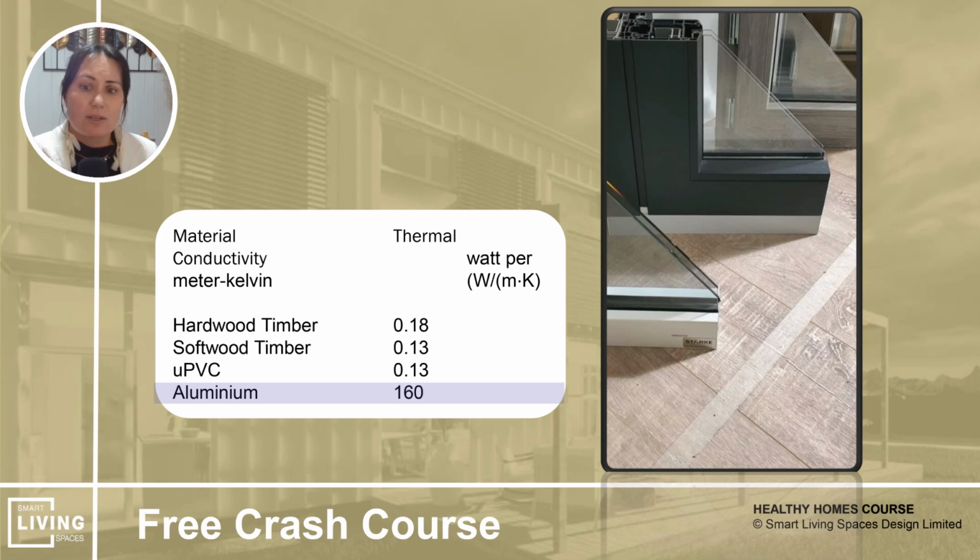Now, what that means is most aluminium joinery companies are now set up for this. So if you want single glazing or non-thermally broken aluminium, it's going to be more expensive because it's going to do a special run. It's also a lot more poor performing. So I wouldn't bother. Timber is expensive, but it's really good for performance, and UPVC is holding its ground on the market, and here's why. So I'm going to show you quickly the thermal conductivity values for these three materials.